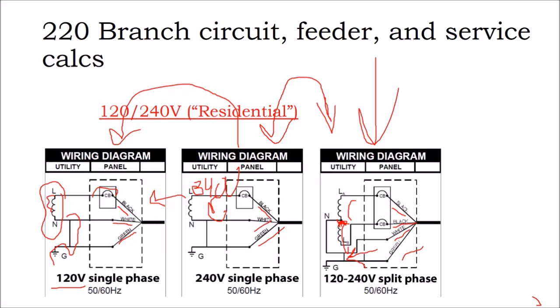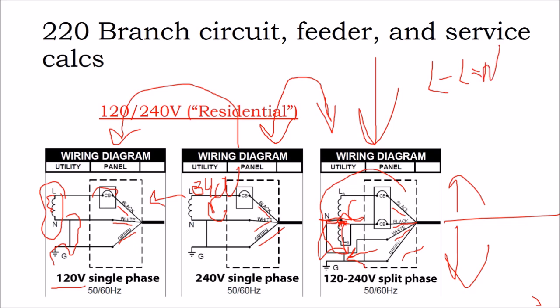And then sometimes there's a concern about your loads being mismatched, because what that means is when your loads are mismatched, you're going to have more current flowing through this neutral line. You know, the neutral kind of representing the difference between leg 1 and leg 2. And so if these are not equal to each other, if the load is not matched, you get somewhat of an energized neutral flowing to ground, draining that current out and keeping the voltage stable between the two separate legs.